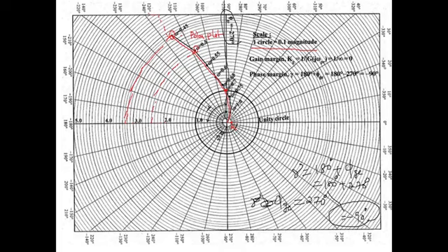So what is the phase margin? Minus 90 degrees, right? Similarly, for finding the gain margin, we have to look at whether any of the points is lying at the minus 180 degree line. See here, is our polar plot lying on the real axis? Obviously no, right? So no points will touch the minus 180 degree line. Therefore, the magnitude at the real axis could be 0. That means G of j omega at the phase crossover frequency, or the minus 180 degree line, could be 0.